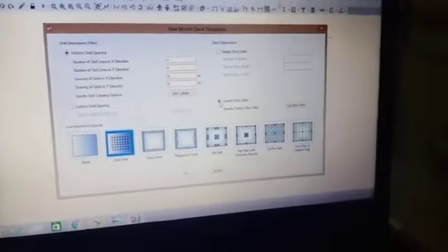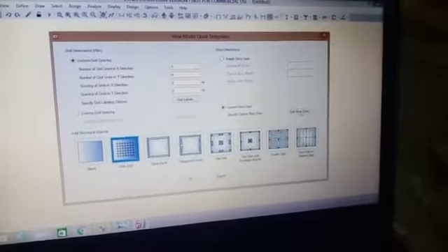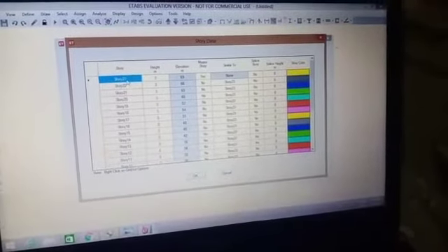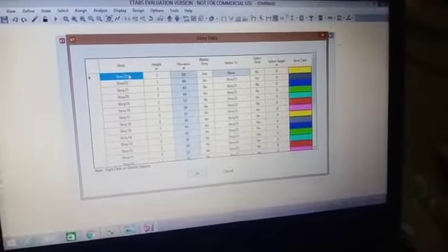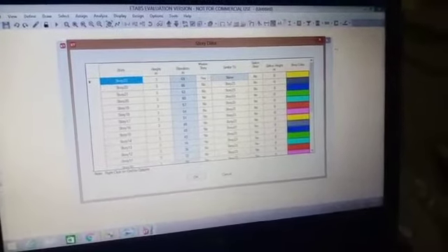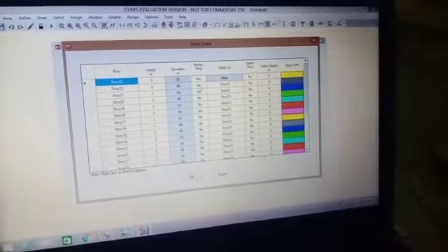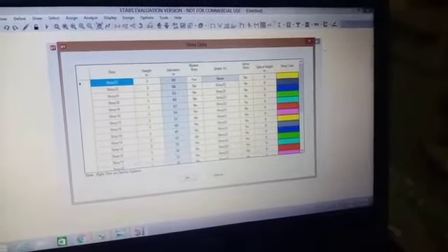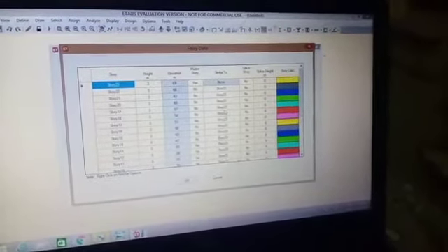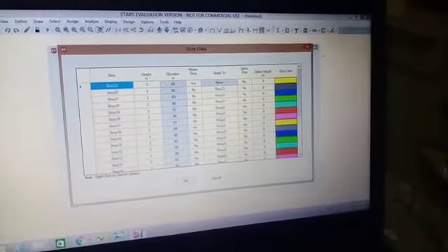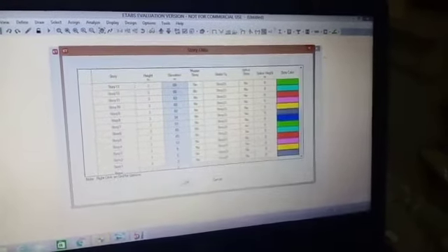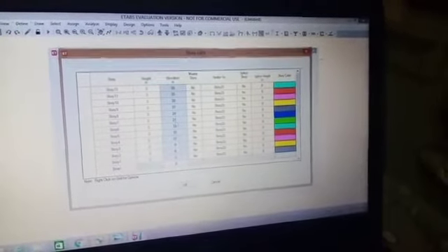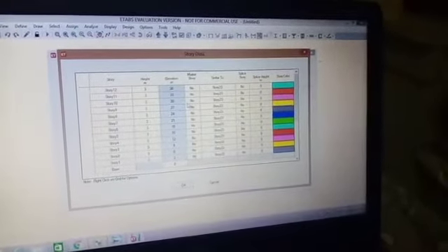And now choose the edit story data option, and now here story number 23 is the master story for all the remaining stories, and all these stories are similar to story number 23. Now what we have to do here is to create different sets of the stories which are supposed to be similar by changing the master story.